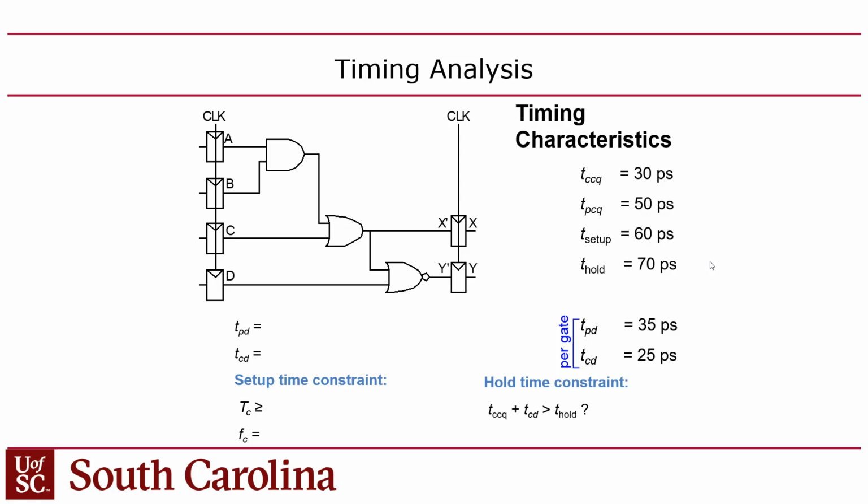They have timing for every single component in the FPGA, of which there are hundreds, if not thousands, because there's LUTs and DSPs and the routing fabric, the switch boxes on the routing fabric, and the I/O pads. All of those things have these timing characteristics. And what ends up happening is that when you download Quartus, what you're really downloading mostly are all these technology parameters, right?